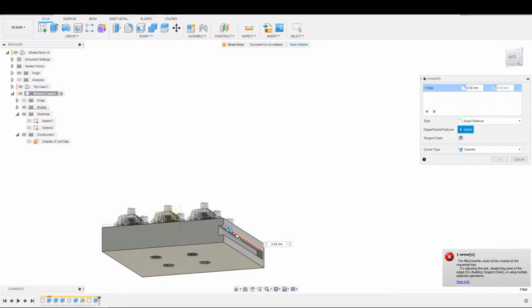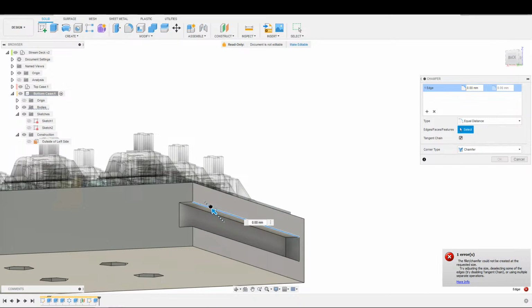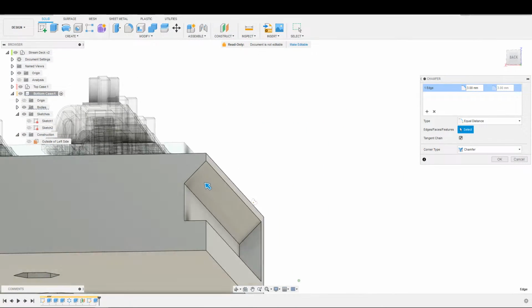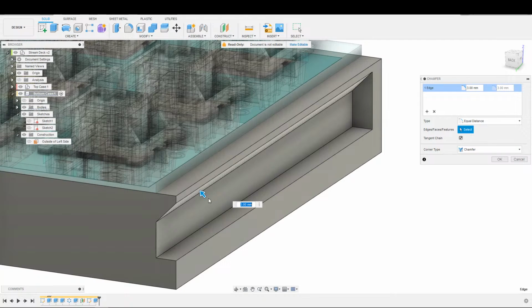We don't want to, okay, never mind. It's not going to let me exemplify. There we go. We don't want to do something like this. Again, just going corner to corner here, though. So getting this to there. We don't want to do this because obviously the rail just slips up and out if it has any flex at all. If it has any flex at all, it slips in and right out the top there. If it didn't have flex, that would be a different issue. But it unfortunately does. So it would end up popping out of this, and what that means is that we're going to have to include supports inside of this overhang.